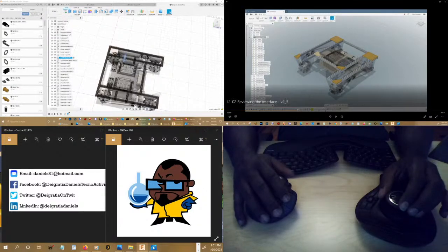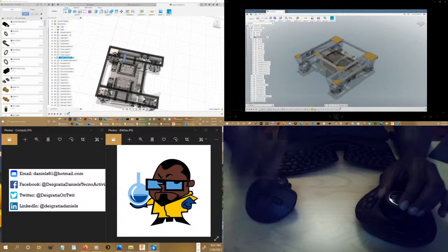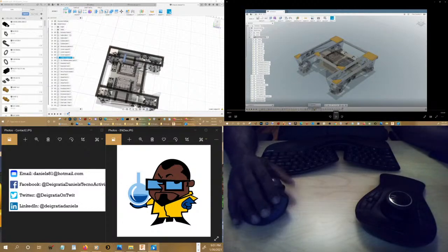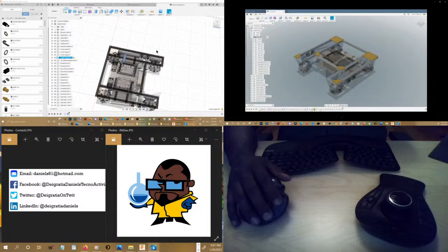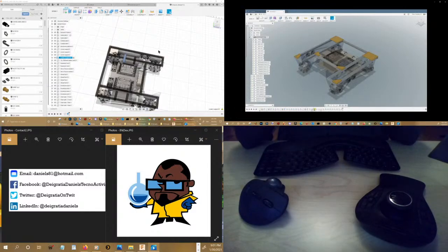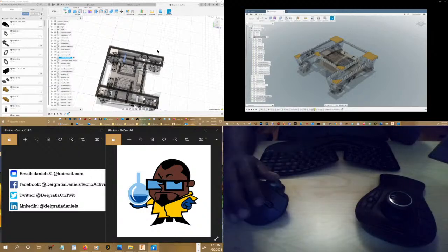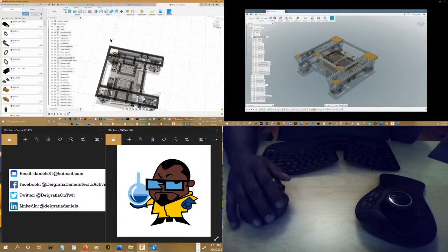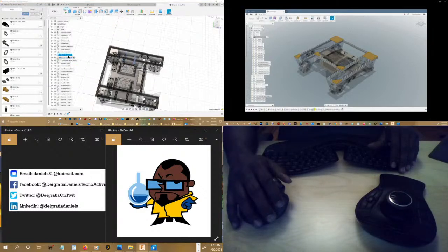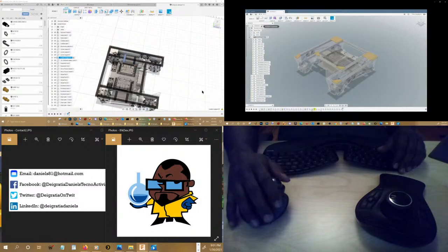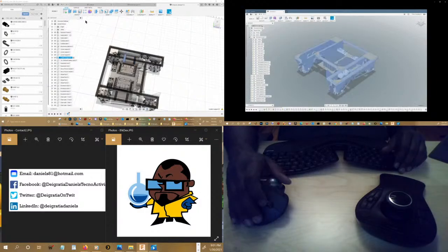Okay, to continue on with the video, we're 2.5 minutes into the video. If the feature has any sort of difficulty, it will be displayed either in yellow or in red. Yellow indicates that there is a problem, but it's not interfering with the function of the feature. This allows you to know that something needs a little attention, but it might be possible to address it at another time. To activate the top level of the assembly, go back to the top level of the browser and select the Activate Design button again.